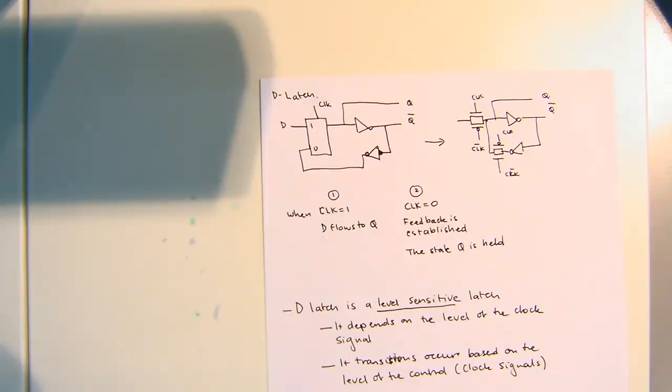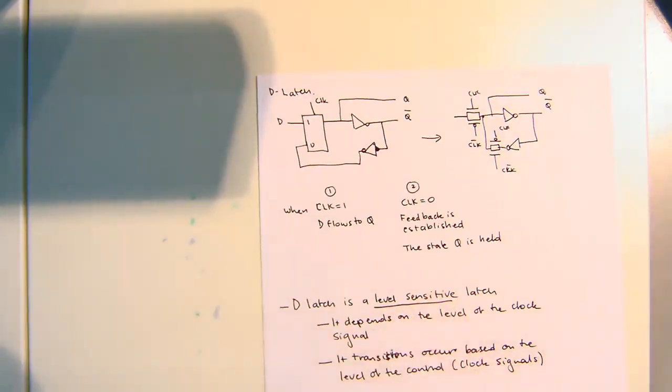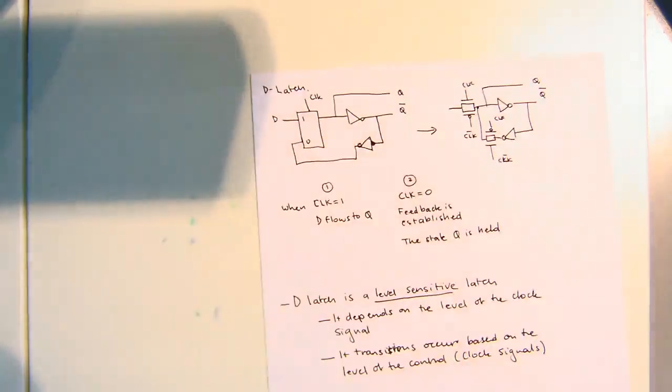Now, okay, so I've written level sensitive. Did you know it from the course or did you actually see it here? From previous. Okay, good. All right, good. Okay, that is absolutely right. So what we've got here is that latches essentially maintain their state, but they critically depend on the voltage of the clock, right?